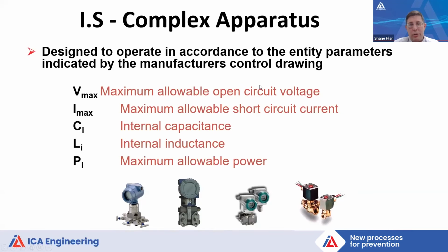That is not true, though, when it comes to other things like transmitters, other types of lights. Certain other things have to be approved and tested that they can't electrically or thermally cause an ignition situation to occur. So they must have the approval by an approval body that says, this is an intrinsically safe transmitter, as an example, and it must be combined with a barrier or isolator and the right calculations for the cable to make sure that the system as a whole in total is an IS system.